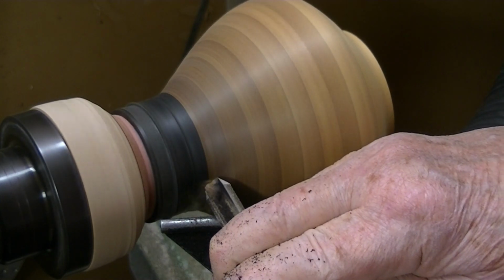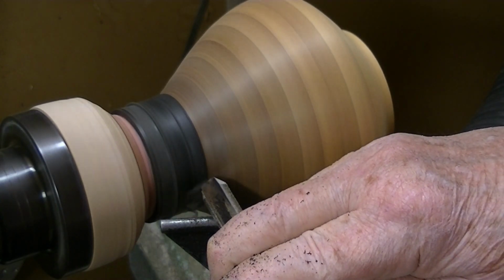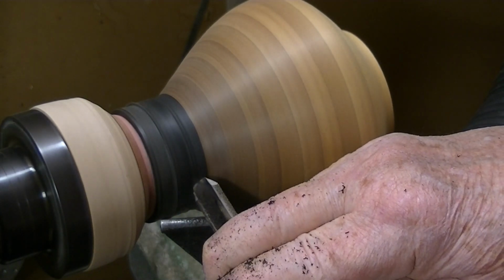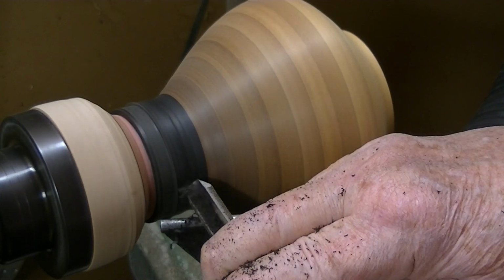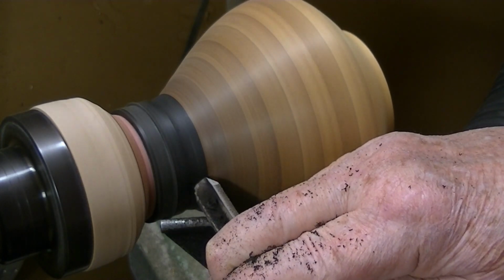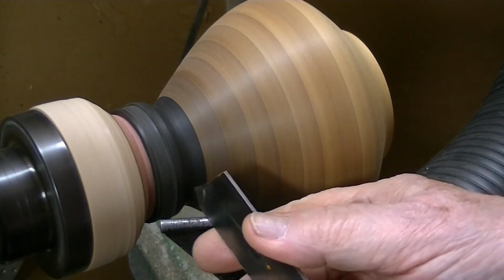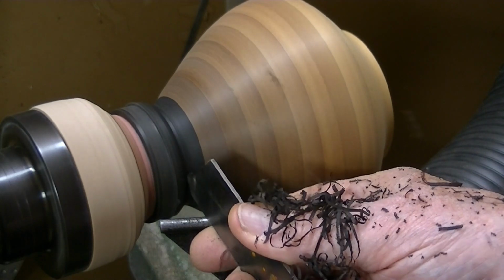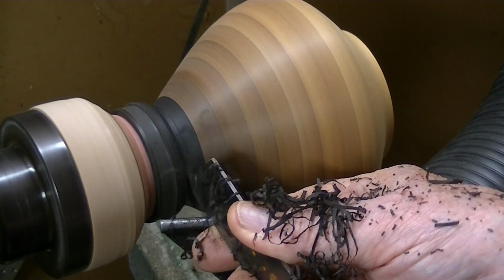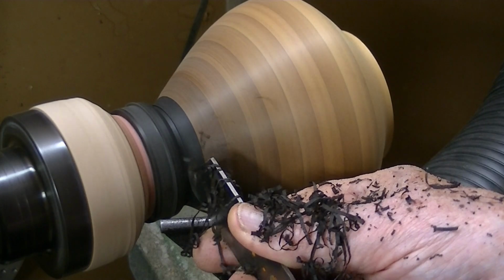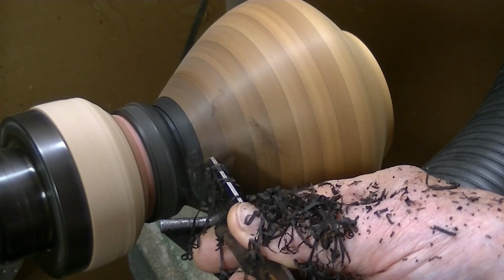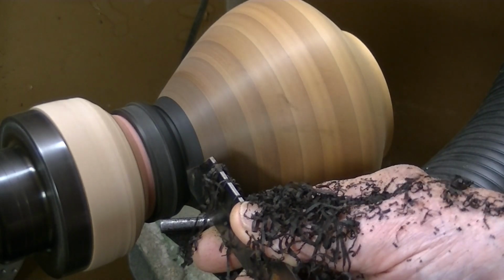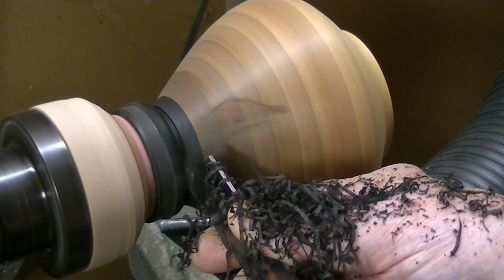The ebony is an end grain piece, so I'm hitting side grain, end grain, side grain, end grain. And I want to be careful that I do not chip or catch on any of that end grain as it comes around. So I'm slowly removing the unnecessary exterior wood. And now I've decided where the base is actually going to be in a few parting cuts here. Not deep, but just enough to mark off where the end of the vessel is going to be. It helps my eye see the finish bottom where it's going to be. And you can see that I'm just making a few light cuts here into the ebony.